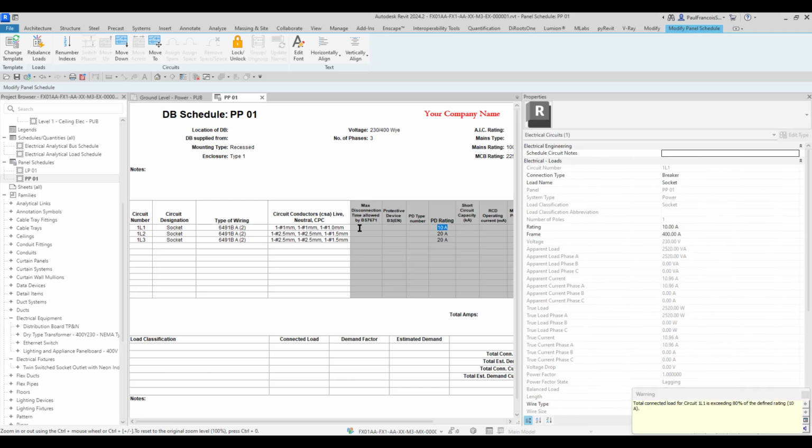All right. Or if it wasn't 20, like it is now, and you don't know whether it was triggered, change the 20 to 30, change it up, and then change it down again. And if 20 amperes wasn't a big enough breaker, then it would inform you as such. So at the end of the project, maybe just go to all the 20 amps, change it to 30 amps, change it back to 20 amps. Is there a warning? No. Next one. Change it up to 30, change it back to 20. Is there a warning?